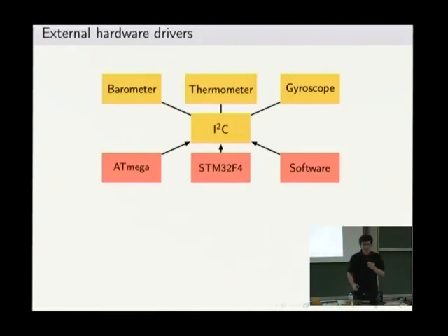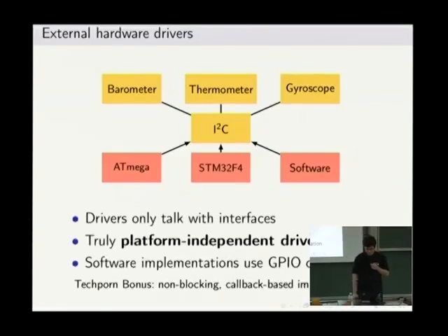In fact, you can even write a software emulator which then uses the GPIO classes to be truly platform independent. So that's what we've done. Also, we don't have time to talk about this, but there's an added bonus point. The entire API is, well, not the entire, but at least for I2C, is non-blocking and callback based. So it's really fun to write these drivers.